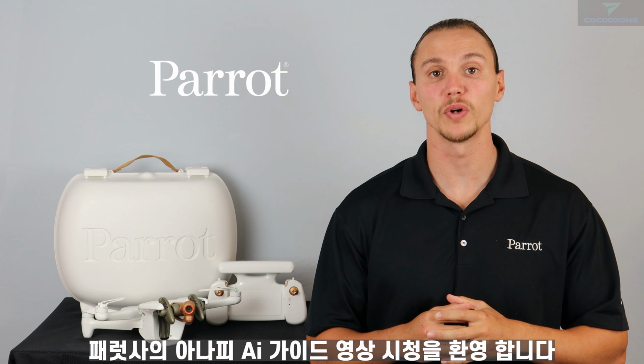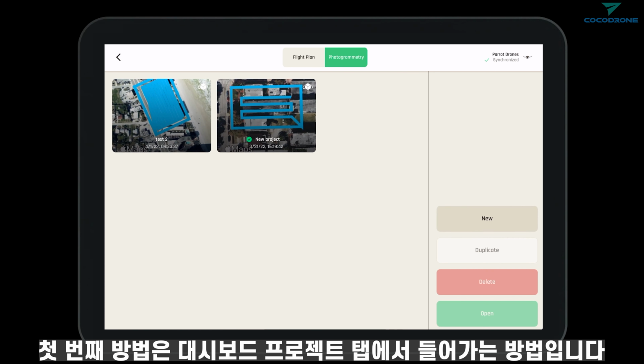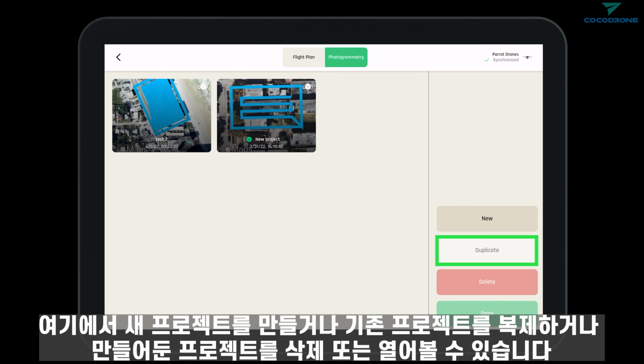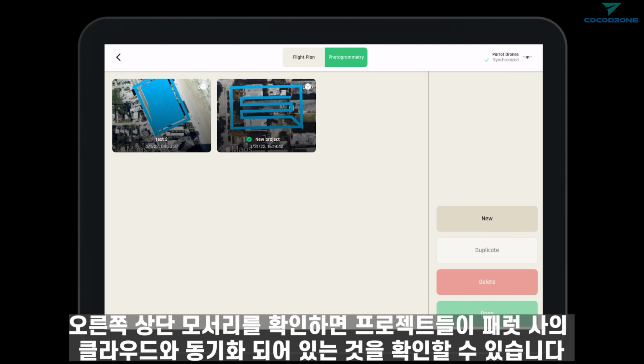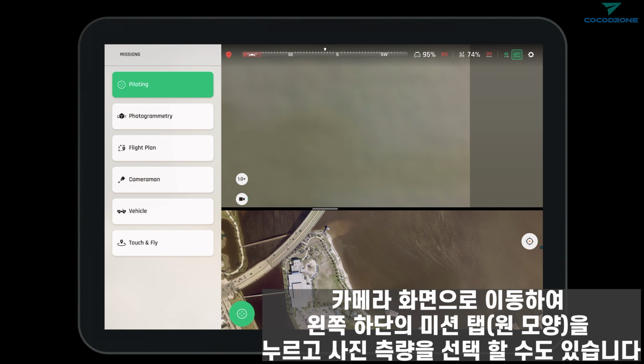In this video, we'll walk through the different photogrammetry options found in the new FreeFlight 7 application. Let's begin. There are two ways to open a photogrammetry project in FreeFlight 7. The first is from the home page. Here we can create a new project, duplicate an existing project, or delete or open what we already have. We can also see that our projects have been synchronized with the Parrot cloud by looking in the top right hand corner. Navigating to the HUD will also allow us to open up our mission tab and select photogrammetry.